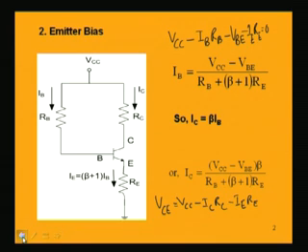Now, one important thing here is that the inclusion of this resistance in the emitter serves one special purpose of self biasing. This circuit is also known as self bias. That self biasing can be understood if we see the consequence of an increase of the collector current due to temperature increase. Suppose the temperature is increased, then the reverse saturation current ICO will rise. ICO rising means the collector current IC will rise.